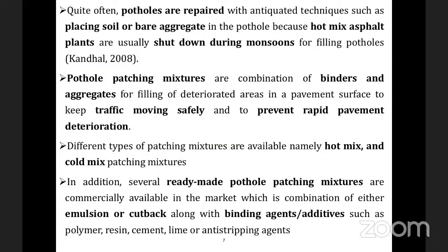So how are these potholes repaired? During the rainy season, BBMP officials shut down the hot mix plants. You know what an HMA plant is? It's a plant where we prepare the asphalt mixture or the bituminous mixture. As the HMA plant is shut down during the monsoon, they use antique techniques like placing soil or bare aggregates on the potholes. This will not solve the problem. So the remedy for this is pothole patching mixtures. The mixtures which fill the potholes are known as pothole patching mixtures.